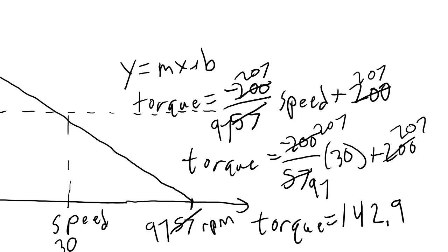Remember that we did not account for the inertia of the motor itself in these calculations. Also, we haven't yet accounted for any kind of payload that the robot might be holding. So in general, once we calculate the torque at the required speed and find a motor that will work, we want to overspec the motor at least a little bit to account for inaccuracies in our calculations.